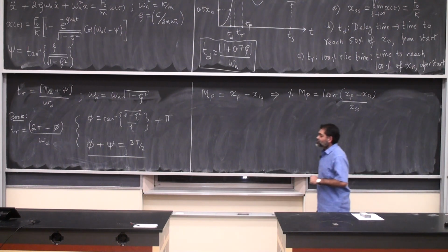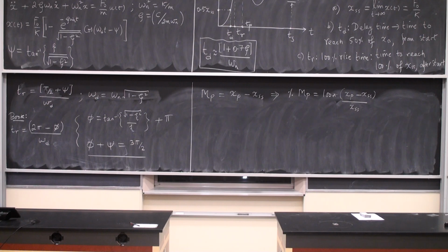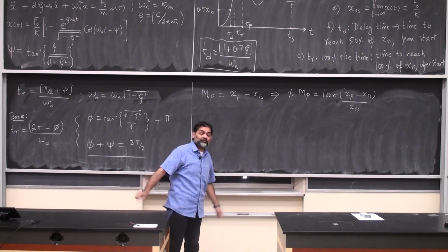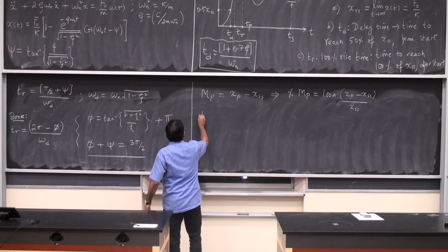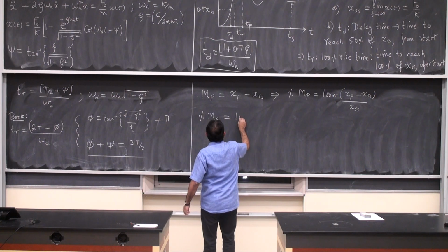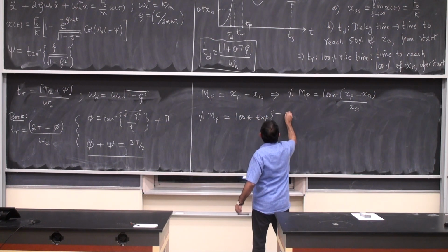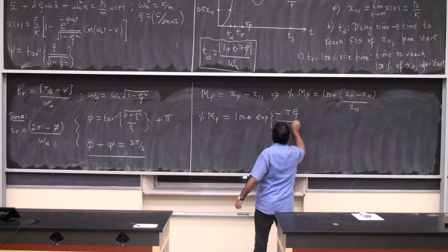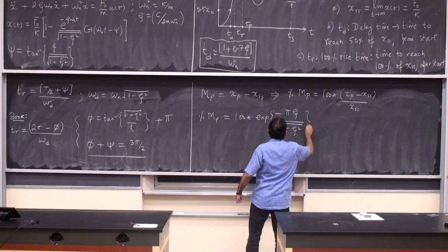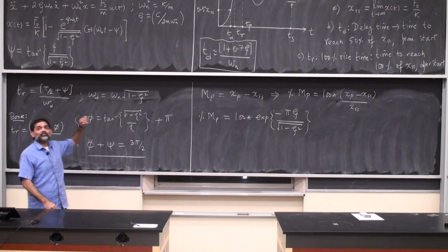Once again, the derivation is there in my lecture notes. We did that derivation last time in class. Okay, and here is the expression for the percentage peak overshoot in terms of the system parameters. So we have percentage MP is 100 times exponent of minus pi zeta over square root of one minus zeta square. Okay, this zeta is the same as that zeta. I just wrote this a little quickly.